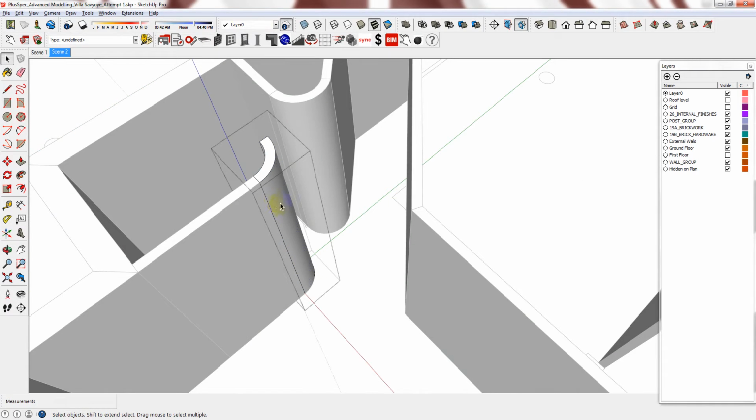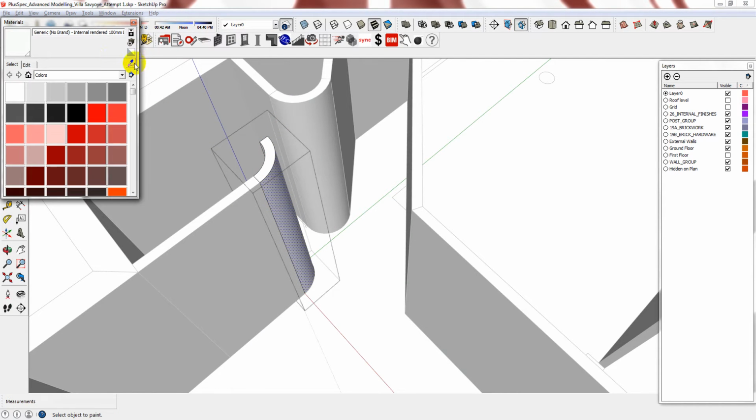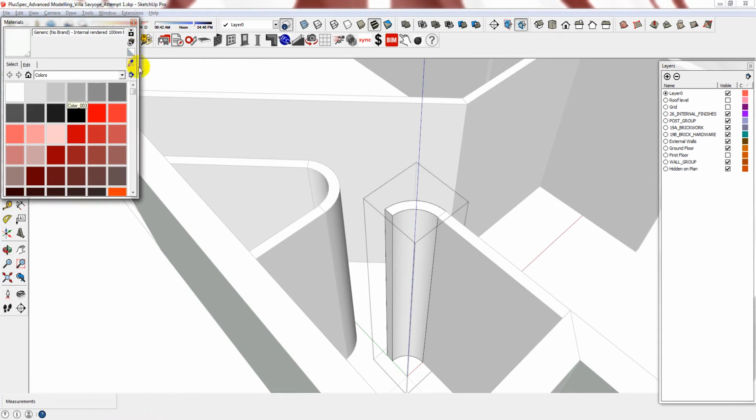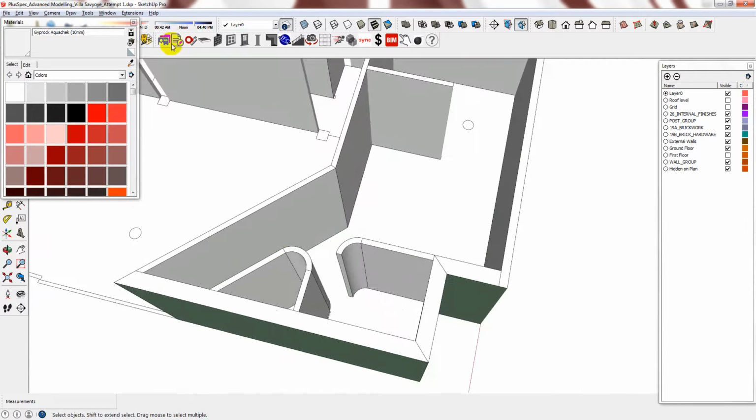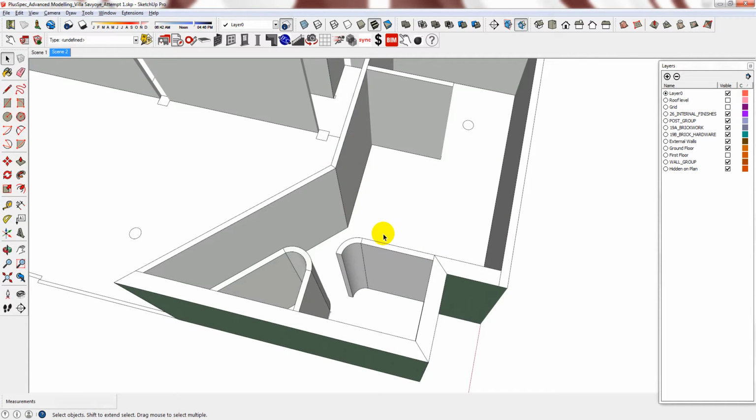Now what I can do is get onto this face and copy this side, and then I want to copy the other side, and now this will be picked up in my takeoff. The shape may not be parametric, but it is still intelligent. It carries all of the required information, and I can still adjust it very easily.